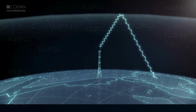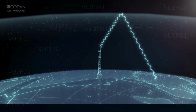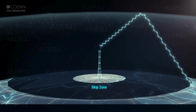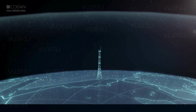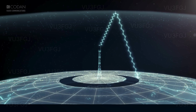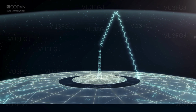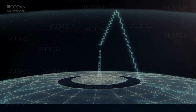The angle of the antenna is responsible for the coverage area as it aims the radio waves which are bounced off the ionosphere. This also creates a skip zone, where the ground wave ends and the skywave starts, where the radio waves are not present as they are not refracted into this area. To reduce or overcome a skip zone, the takeoff angle of the antenna is adjusted. By using a higher takeoff angle for the HF signal, the ionosphere is used to refract the signal back to Earth at a shorter distance. All sorts of voice, data, or signals can be sent using these waves.